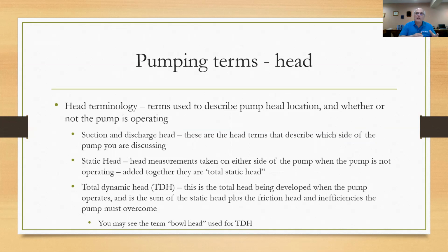So if I'm on the suction side of the pump, the water is coming in. That water is available to the pump. That's suction head. It's either high or low. Coming out of the pump is now discharge head. So you're on suction side or discharge side of the head.